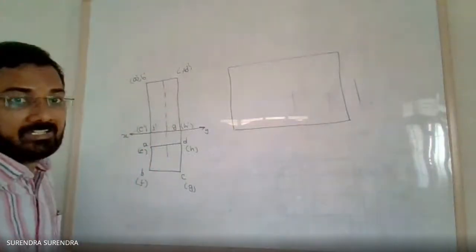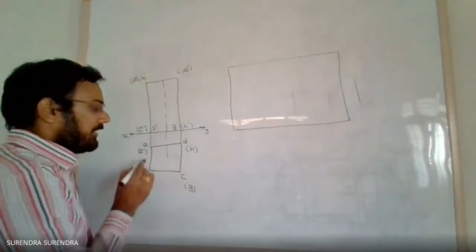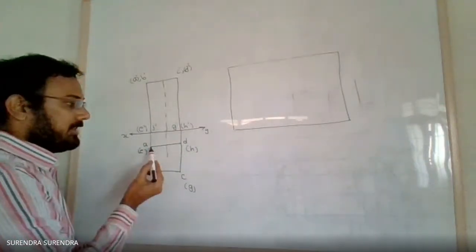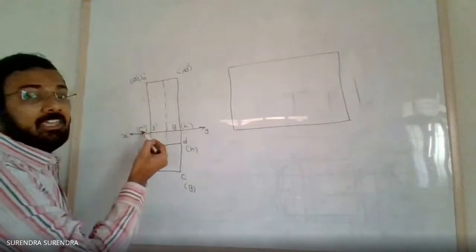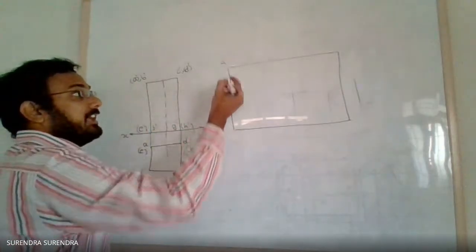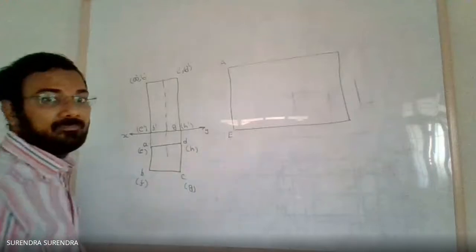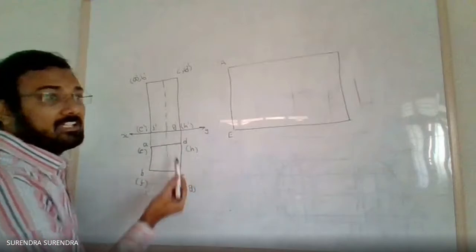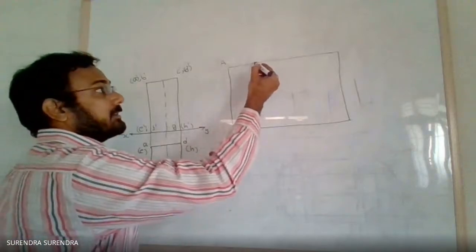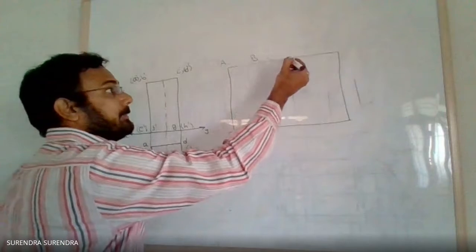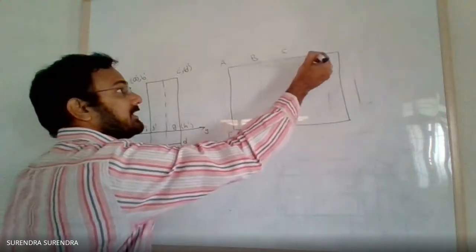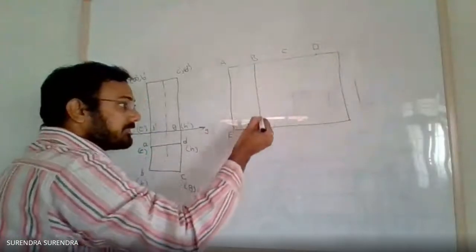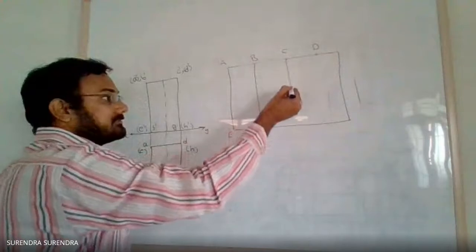Complete this rectangle. Now, assuming that we are opening this solid based on the corner A. So what are these points? A, E. So mark this as A, E. Now, take the distance equal to side of this square, 30 mm, A as center, mark point B, B as center, mark point C, C as center, if you mark point, getting D. Draw the parallel lines.